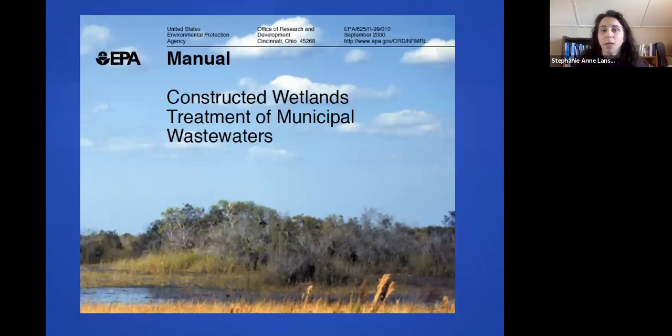There are a lot of wetlands built for municipal treatment, but not always. Actually, one of the biggest builders of wetlands is Ducks Unlimited, more for habitat. But again, a lot of municipalities do build wetlands for municipal wastewater. This would be the tertiary treatment, or sometimes even the secondary, but usually it's after settling of solids, and then it would go through a wetland.